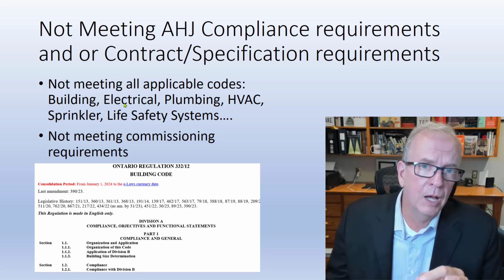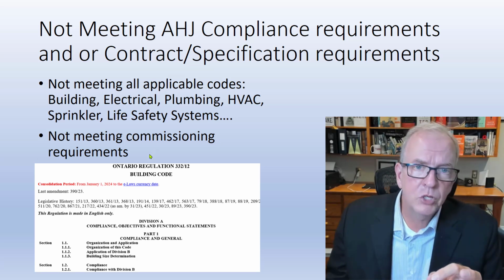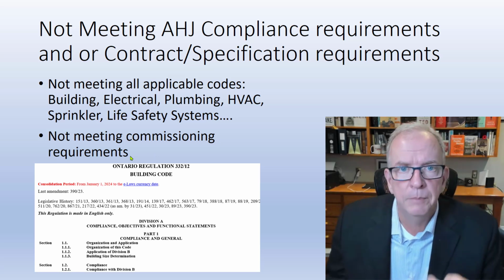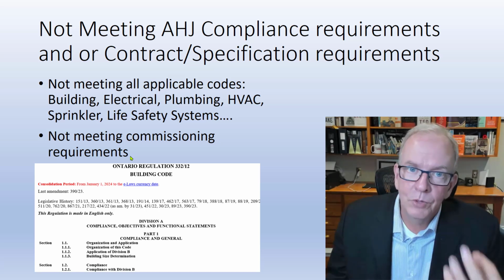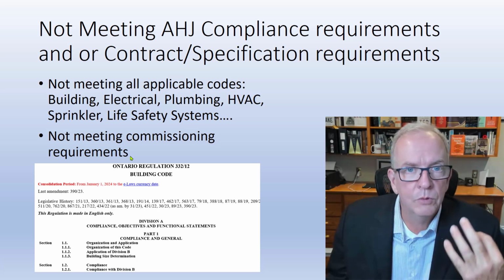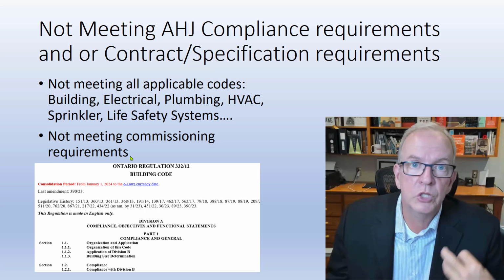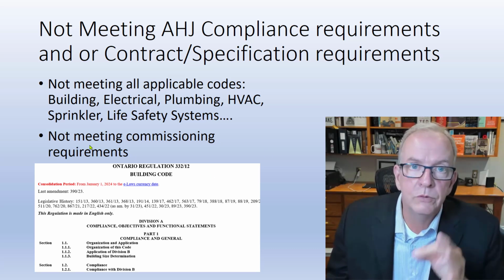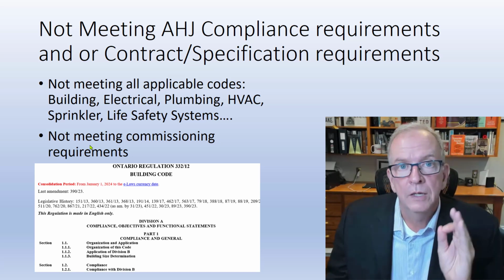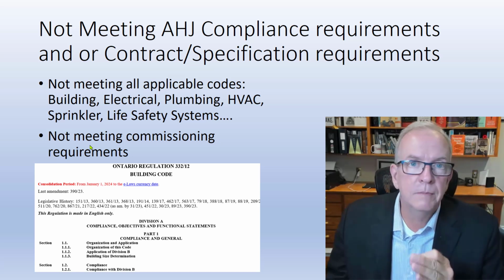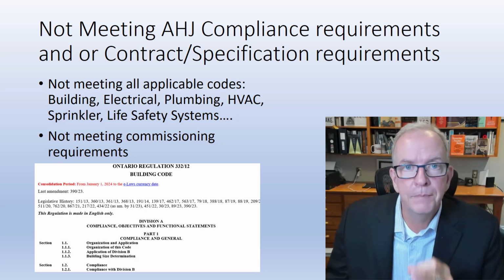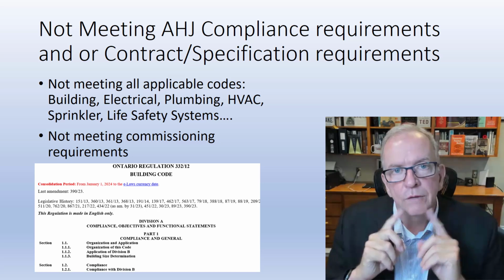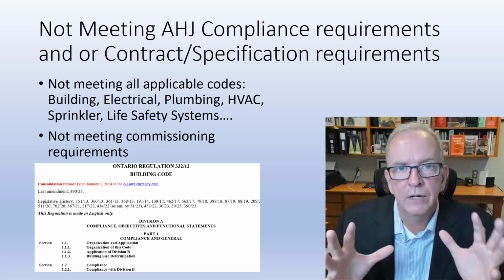When we talk about commissioning requirements, the best time to start planning for commissioning a building is when you start, at the earliest possible time, in pre-construction and the design phase. Start planning for how you're going to close out the commissioning, so when you get there, things pass, or if something doesn't pass, it's not far from being able to pass. These are important things to consider. So I think that's the first unpacking of the 8 areas of waste.